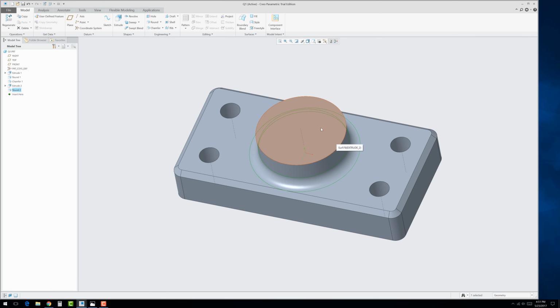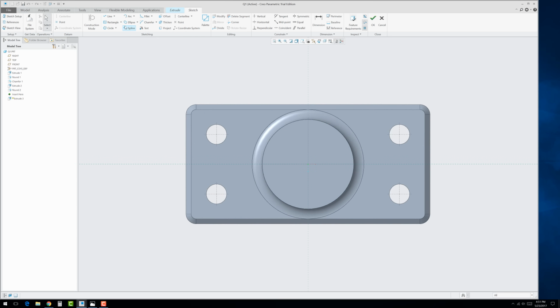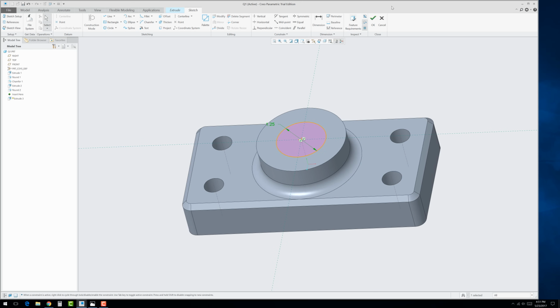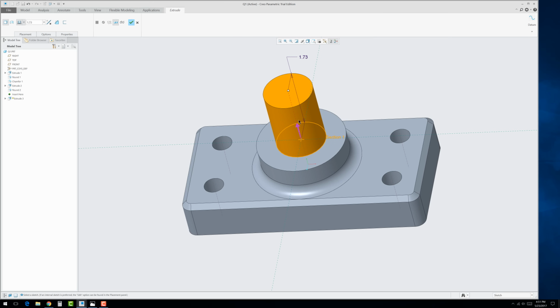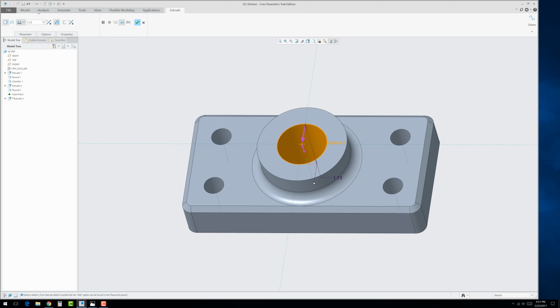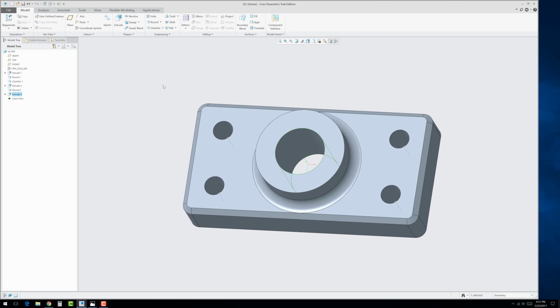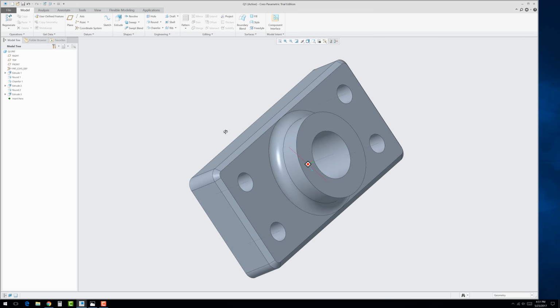Okay, now we could put the hole on here. So again, you can select that face and go to extrude. There is a hole tool that we could use, but we'll learn that in exercise 4. That's coming up in about a couple weeks. Click on the center, drag this out. This is going to be 1.25 for the diameter. Hit OK. Notice this. If you flip it, it will automatically go to cut for you. But then over here, you just have to select through all, which is to intersect with all surfaces. Hit the apply button, and you're done.